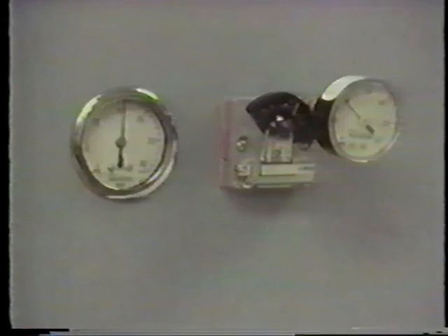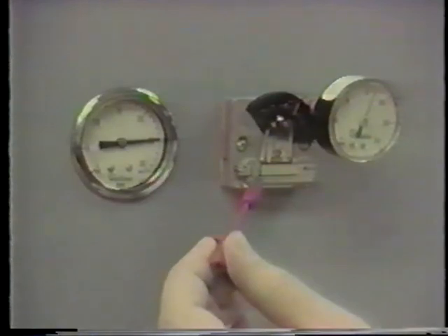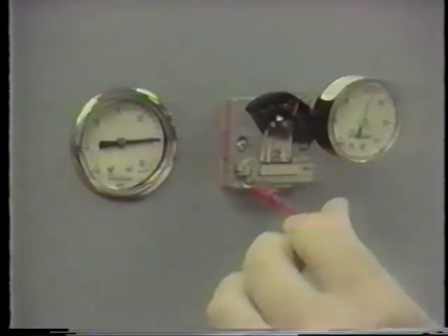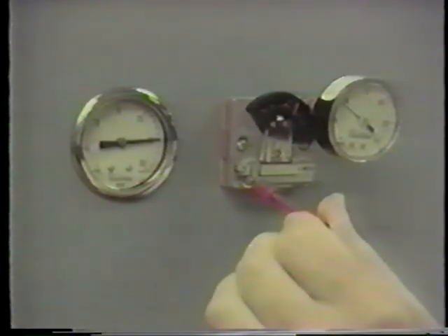The dual bimetal summer-winter thermostat is calibrated in the same manner, with the exception of the winter set point. Increase the main air pressure to 25 psig. Use the calibration tool to adjust the winter calibration screw until the branch line reads 9 psig. The winter set point dial must read the ambient temperature within 1 degree Fahrenheit.